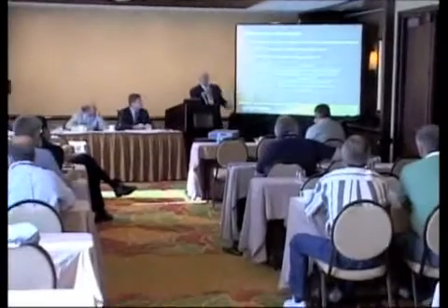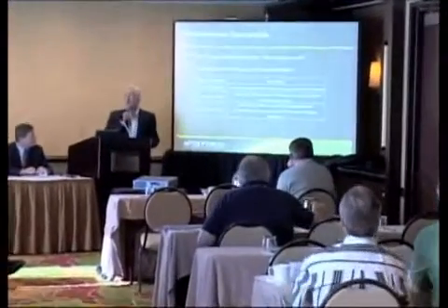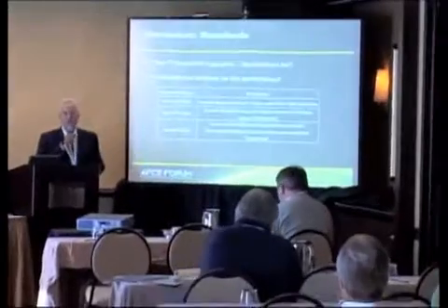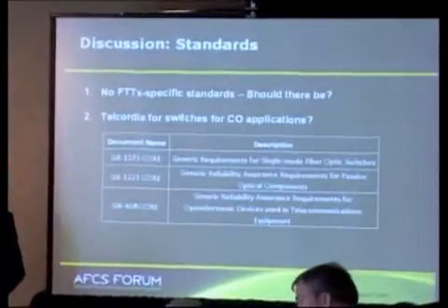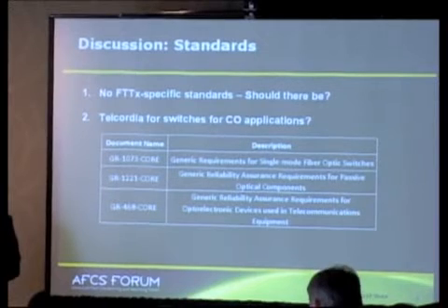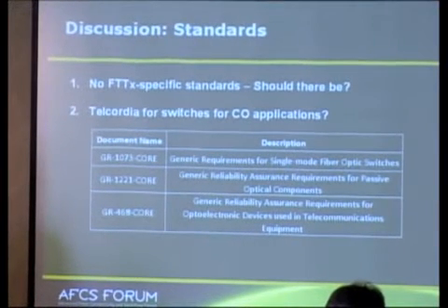It's a very good question. On this chart, I have some standard requirements for optical switches. These are Telcordia requirements, and all optical switch vendors need to qualify to these requirements. Some of these involve temperature cycling between very low and high temperatures, and shock and vibration tests.